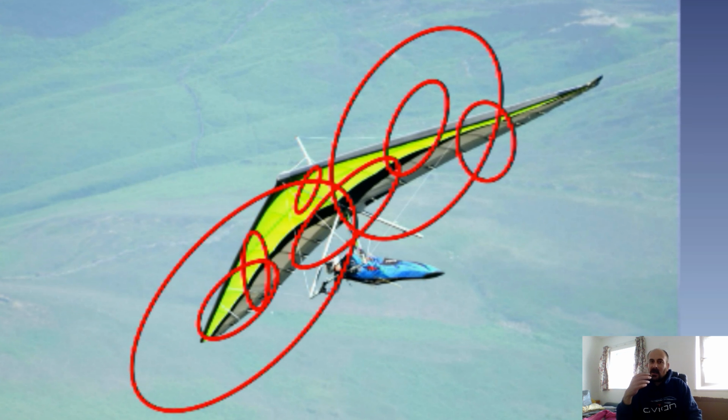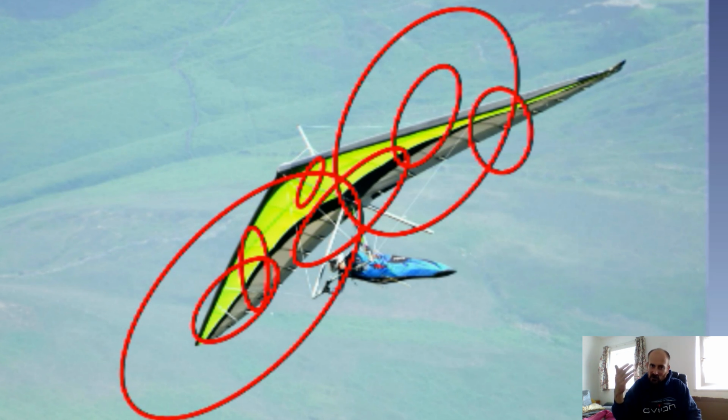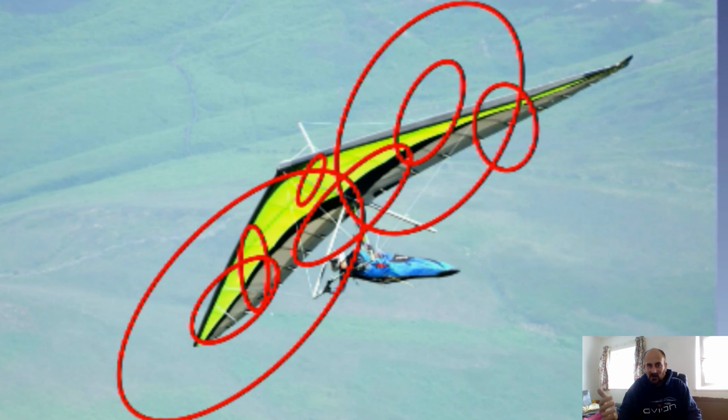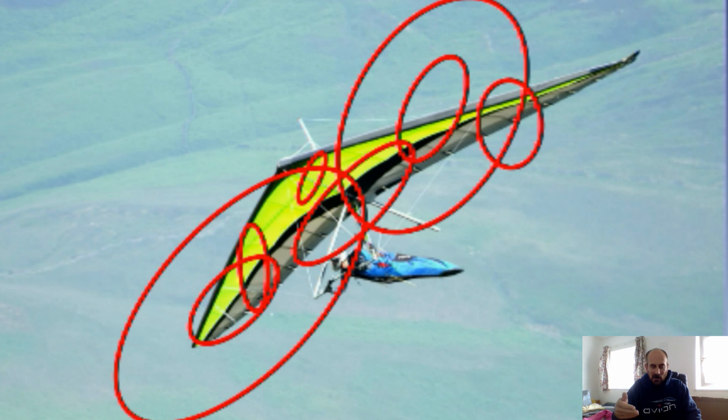And we've got the VG, but even beyond that, as you change the angle of attack of this wing, you're going to be changing the pressure distribution, which is changing the load on it, which is changing the shape of it. So it's a really difficult system to analyse. I mean, on normal aircraft, obviously a wing bends and twists when you put load on it, but the amount that a hang glider wing does this by is just much more than other aircraft, and because it is a tailless flying wing type aircraft, that also adds complexity. So this really is quite a complicated aircraft to try and design by any standards.